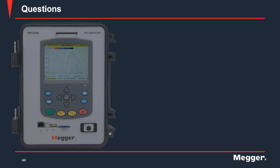All right, let's jump into the Q&A session. Our first question I'm going to be directing to Mr. Andrew Sagal. Andy, we get a lot of DC bus overvoltage even when equipment is not running. Filter seems to help, but we still get them when the filter is on. Where would you look for power quality issues? The transformer is already tapped down a little, but it hasn't helped.